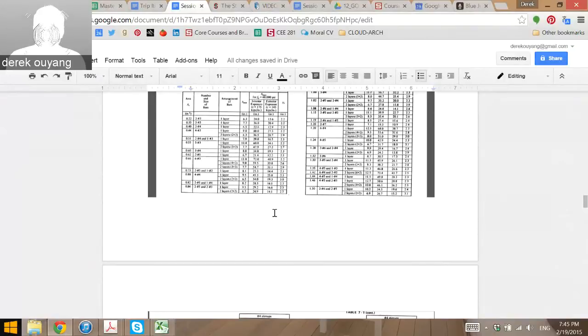And then this is A, which is something less than C, right, by the factor of beta 1. So all those formulas should be really easy to grab. And then your actual formula that you deal with is, first of all, you're going to set Ts equal to Cc, right? So Ts equals Cc. This is As Fy. This is that Whitney stress block, right? So it's going to be the area BD, and then the Fy equivalent there is going to be that 0.85 F prime C. And I'm guessing, what am I missing here?